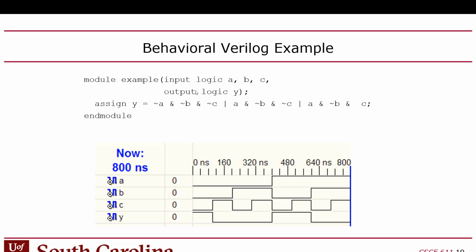When you simulate this, the way you view it working is through a timing diagram like this. You'll have this plot where the horizontal axis represents time, and each one of these signals is arranged as a row along the vertical axis, and then each signal can be designated as being 0 or 1. Now, logic, I'll talk about this in a minute. SystemVerilog does support multi-bit logic, and if these were multi-bit signals, then they wouldn't be 0 or 1. They would be a value within the range allowable by the number of bits you have.